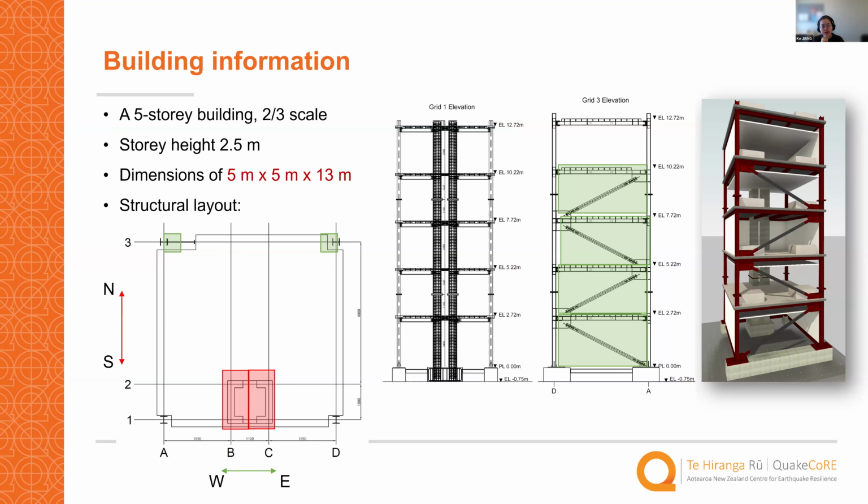And we are always curious to see what the lateral load resisting system of this building is. Along the north-south direction, the lateral load resisting system is mainly contributed by this concrete core wall. There are two C-shaped core walls linked by several coupling beams. That is the main contributor for the lateral load resistance in the north-south direction.